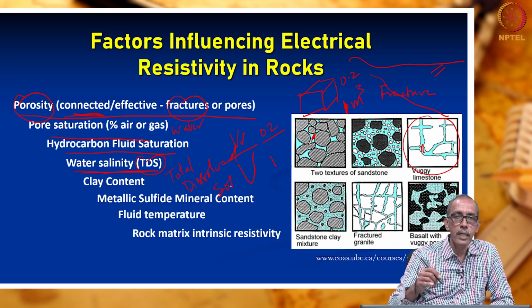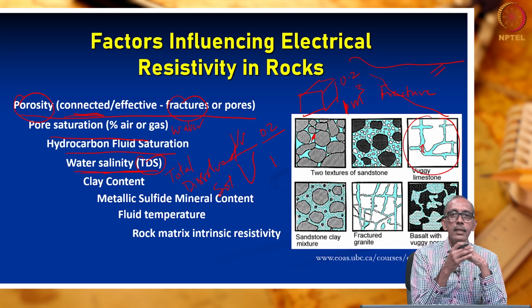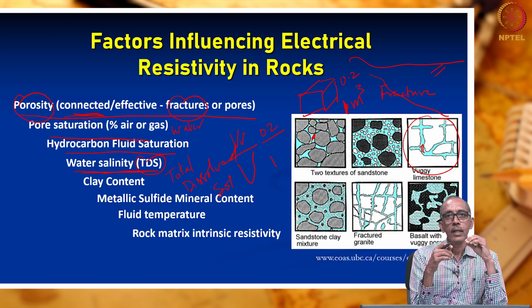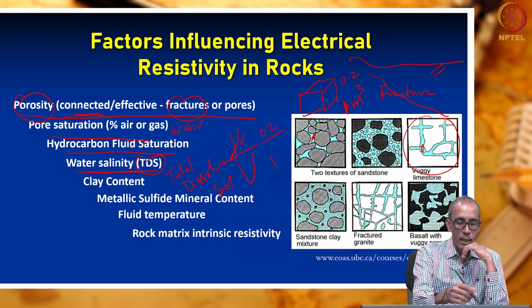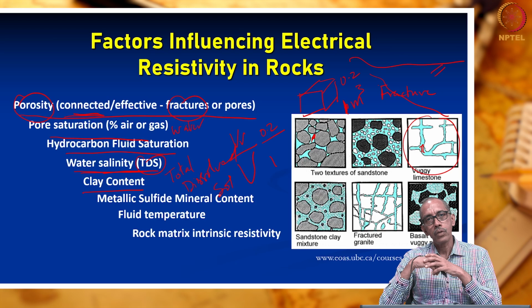Total dissolved solids: if it is more in the subsurface groundwater, then the resistivity will be less. So this is one of the factors that affect the measured resistivity. Then clay. How does clay play an important role?